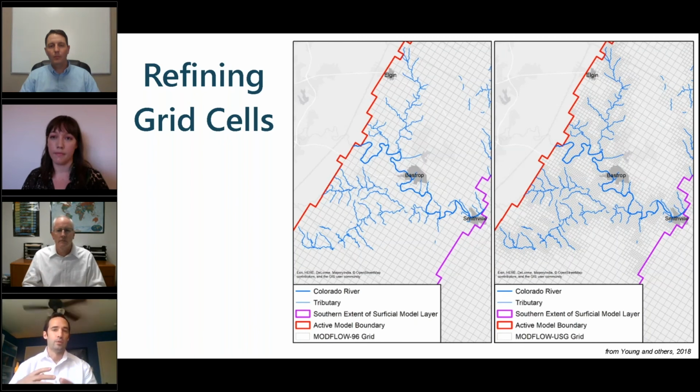And I think it's important to evaluate the known or assumed variation of hydraulic properties and stresses of the system that's being simulated and compare that to the size of the cells, along with the intended use of the model and the importance of the features being discretized. It affects the evaluation of whether the model is discretized appropriately and whether important features are missing that would cause a systematic error or a bias, if you will, in the simulation results.